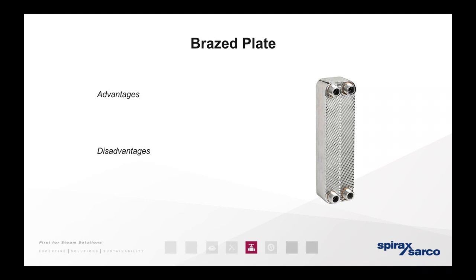Now, the reason this is quite an in-depth question is that we need to understand if this is a trapped heat exchanger or if this has got an APT, automatic pump trap. Because for me, if you're heating anything below 100 degrees Celsius, we're probably experiencing a stall condition on this heat exchanger. I'm not sure if you want to interject there and maybe give an answer as well,